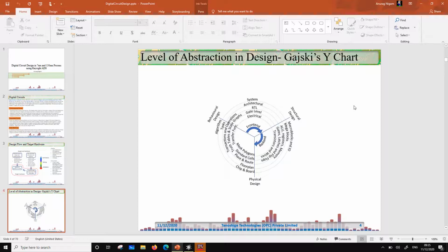Then there is placement and route. This is also automated. If you do it manually, as we do it in RF circuits or analog circuits, then it is going to be very involving because the number of transistors in digital circuits is much higher, right? So again, even if we are doing it for small circuits, we do what is called floor plan. We decide where which standard cells are going to be located, how they are going to be oriented, and then how they are going to be routed, how they are going to be connected together with traces. This would be coming under floor plan, right?